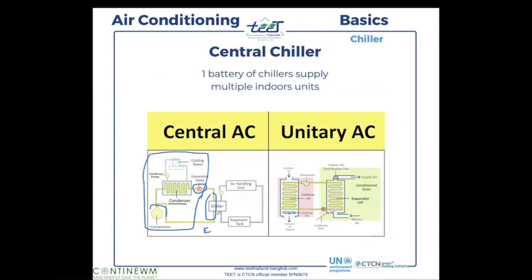So it's cooling water. Instead of cooling air, it's cooling water, okay? So we use the refrigeration cycle not to cool air, but to cool water. They are exactly the same mechanical parts, exactly the same system, just adapted to cool water.